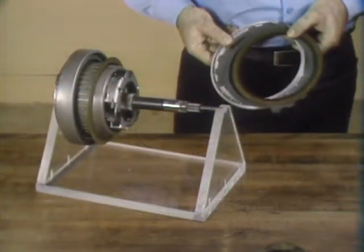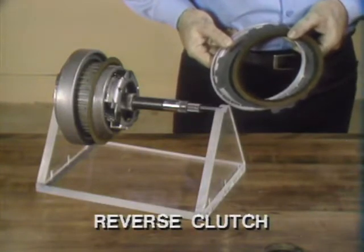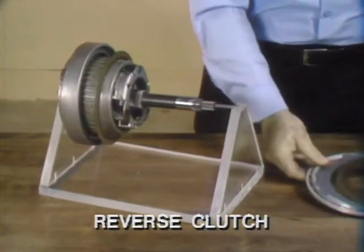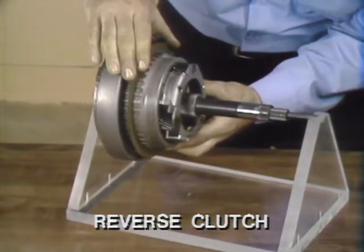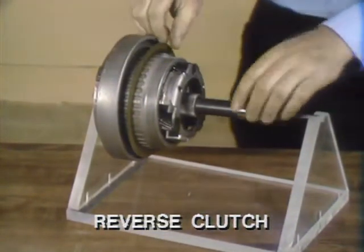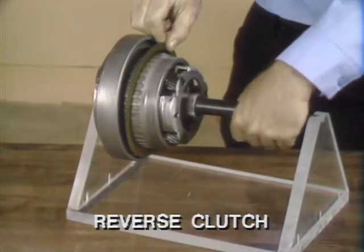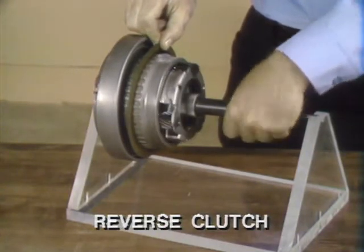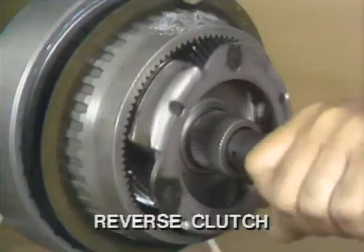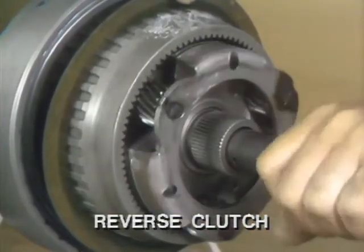Next, let's look at the reverse clutch. The reverse clutch has its steel plates and piston installed stationary in the case. The friction plates with internal splines fit over the splines on the ring gear, right next to the intermediate clutch plates. When the reverse clutch is applied, in reverse gear only, the ring gear is held stationary. With power in through the turbine shaft, the long planet pinions are forced to walk around inside the ring gear.